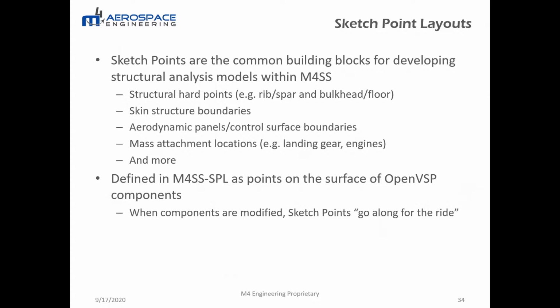One final thing to note about sketch points is that as they are defined as being on OpenVSP components, they will go along for the ride, so to speak, as OpenVSP parameters are modified. This allows Structure Studio to be used in design space exploration applications. So if the model changes, you won't have to go in and redefine all the sketch points. The sketch points are defined with their UW parameters, so they follow along.